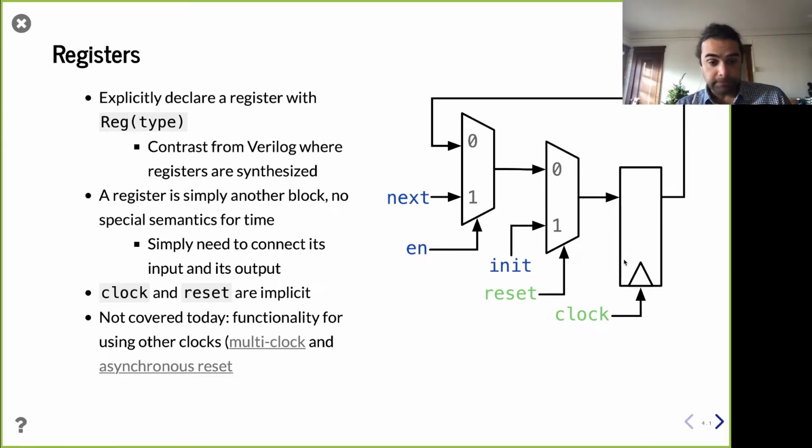Now, this register, every cycle takes this input and makes this output, right? Once per cycle. In practice, that's maybe a little bit too simple. And so we usually add more things onto it to make it more useful, right? For example, you might want to have the ability to reset your register, where if reset is true, you want to load a certain value into it. Or perhaps you don't want the register to change value if the write enable is low. If you want to be able to turn off whether or not updates are possible on the register, you have this write enable signal, right?